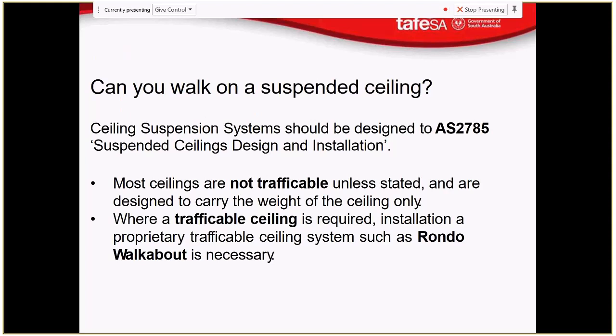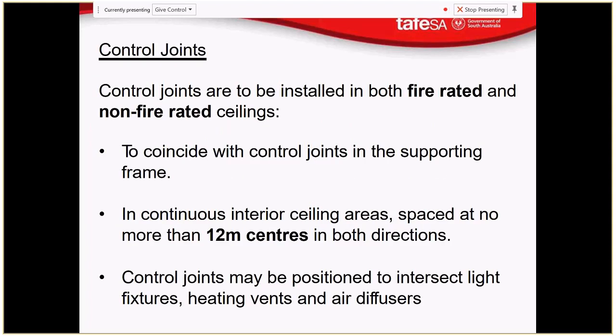Where a trafficable ceiling is required, installation of proprietary trafficable ceiling systems such as Rondo Walkabout is necessary. Rondo is a company that you'll see a lot, and you'll see mentioned in the CSR Red Book, I think. I'm not sure of the ownership structure there, but they are a major supplier and specifier of suspended ceiling systems.